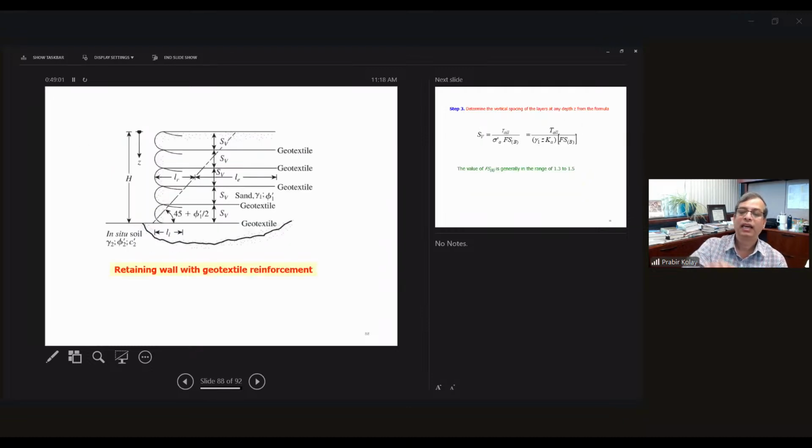And then obviously, when you use the geotextile, there should be some lap length over here. So basically, you see over here, LL. So when you put a geosynthetic material, put a granular soil, and then you put a little bit of lap on the cover, overlap the cover. And then you put a layer of sand again, and then put a geotextile, and then put the lap length over here. So basically, what you need to do is find LE and LR, the same Rankine's failure lines, and then the 45 plus φ/2 angle. So this is geotextiles.